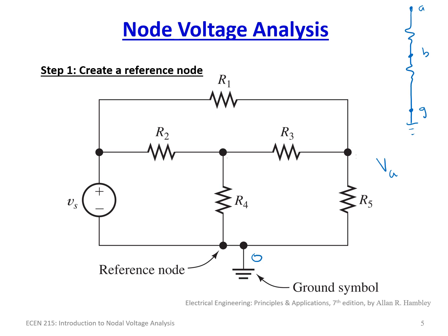Then when I give a voltage VA, it is actually VAG. It is the voltage from here to here. And voltage B at node B would be equal to VBG. It's the voltage from here to here, whereas the other one is this voltage. So it is the nodal voltage to ground, to the reference node, not across the element, but to the reference.